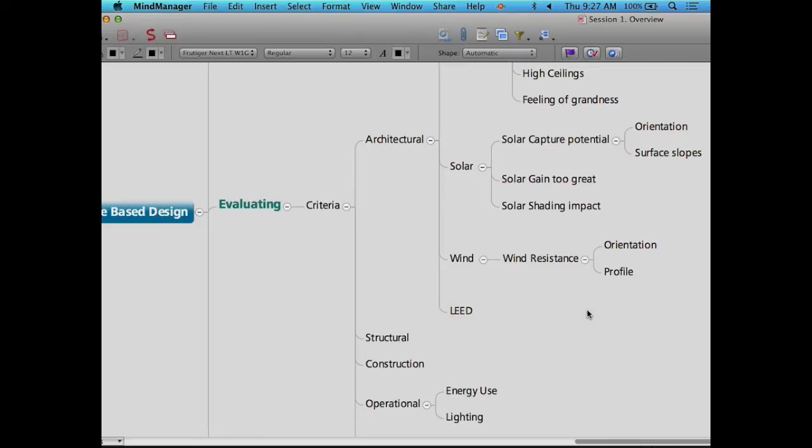There are some fantastic examples now of some of the most interesting buildings. One building that's quite interesting, if you haven't paid much attention to it, is the Shanghai Tower. It's the story of how, by working with the shape of the building and the profile it's presenting, and putting a little bit of twist in the form, they were able to reduce the wind forces on the building greatly, which led to a 25% savings in the structural members. That's a huge cost savings and a very big environmental plus in terms of the material impacts. So we can look at things like that.